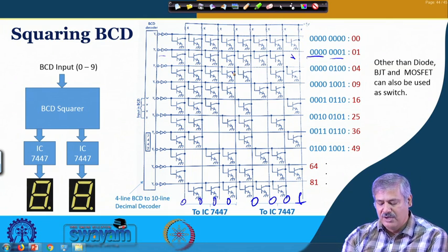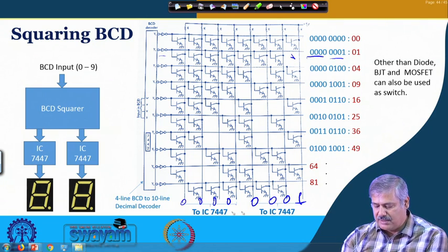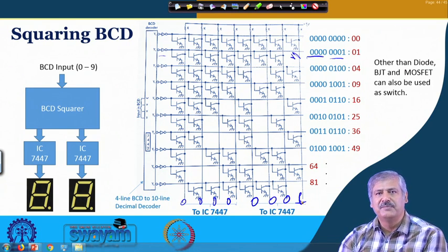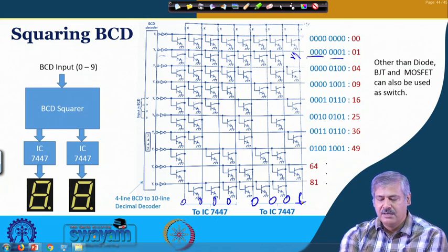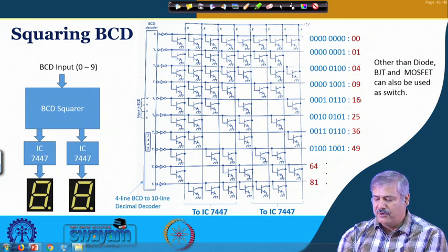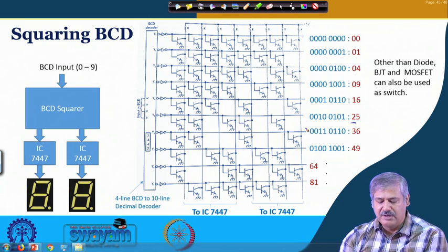So, this is decoded. So, all of these particular places, these transistors will be on, right, up to this. So, the output will be low, that is 0.2 volt, 0.1 volt, whatever the saturation voltage is. Here there is no connection. So, 5 volt, with whatever drop over here because of the load current, it will be logic high, okay.